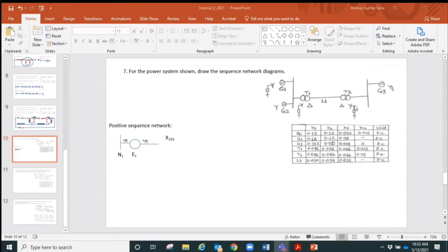And then we go to the next transformer T2. Again, it's connected in star delta configuration. The star side is grounded through an impedance connected to another bus bar where there is another generator possibly coming from another power station, for which the star connection is grounded solidly. It's defined as generator G3.